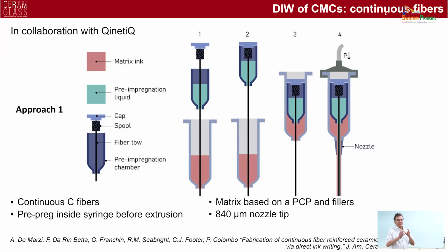So having such a fiber tow surrounded by the matrix is not good enough, because the fibers in this way are not able to sustain the load, as in the case when they are surrounded completely by the matrix. So what you need to do is infiltrate the fiber tows with the matrix, so that you have the entire system that doesn't contain voids.